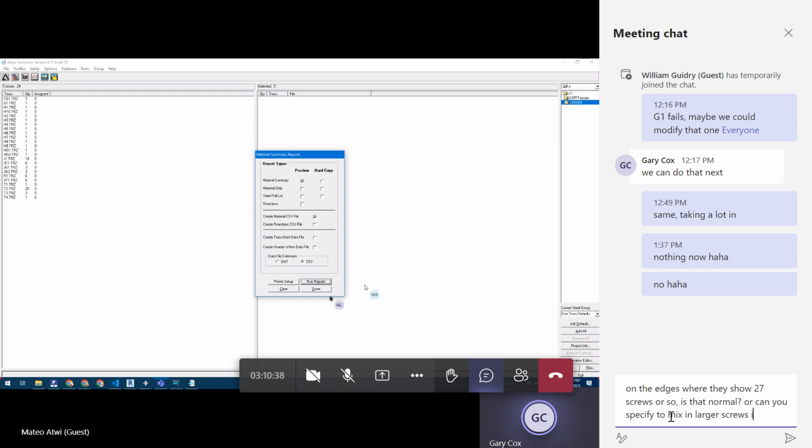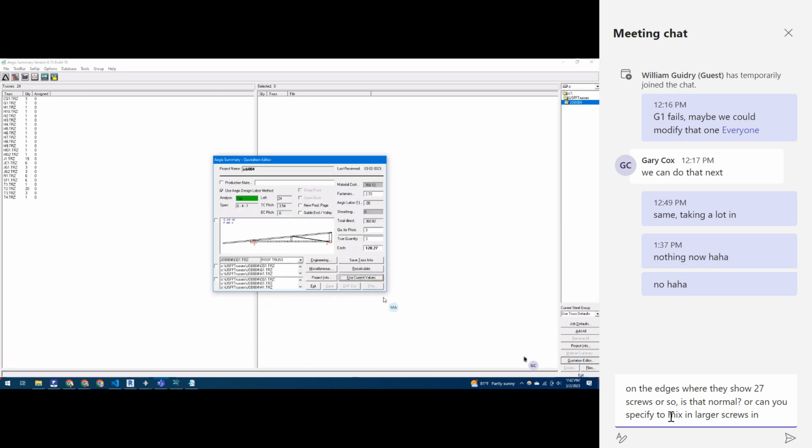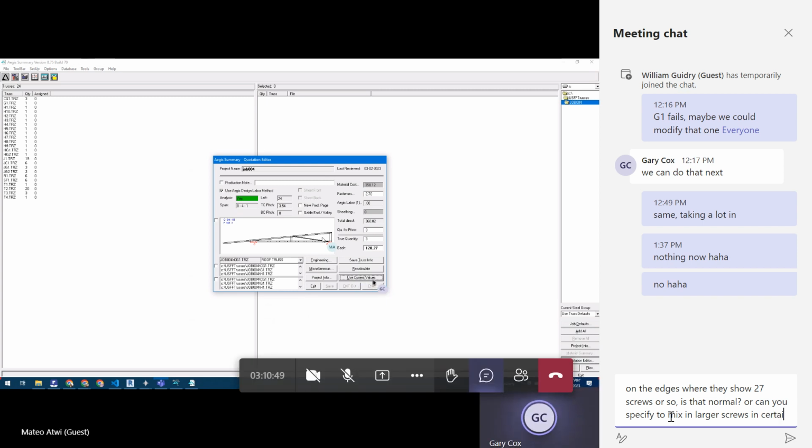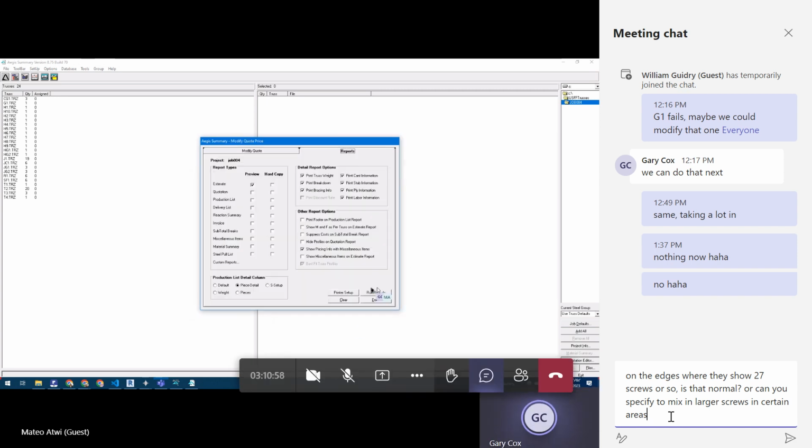Then you close it, click Done. Then now you bring up the quotation editor. In this case, you're going to tell it to use current values, so it'll bring everything in. Then you're going to click the print button. Now you have all these other reports you can print. These are just previews, or you can just do a straight hard copy. Some of the material summary is in both places, but you can only create the CSV from the other one. But it has to go in these steps.